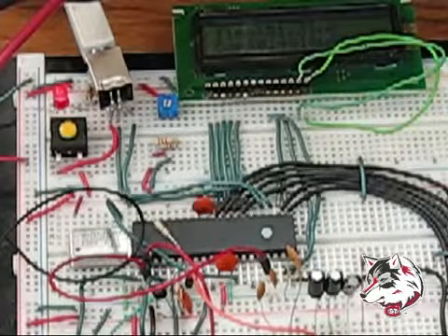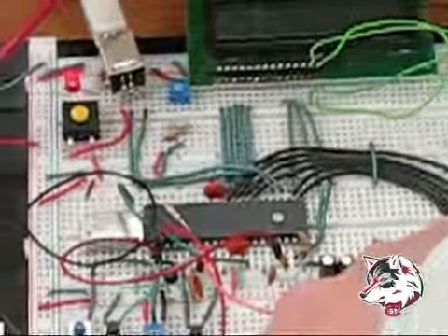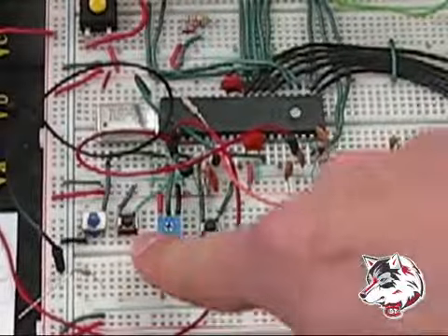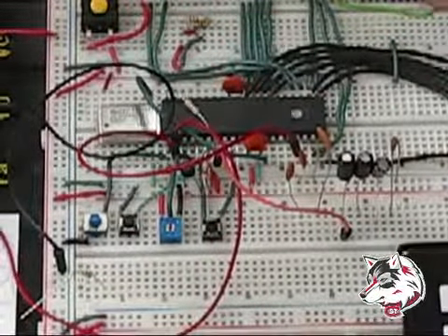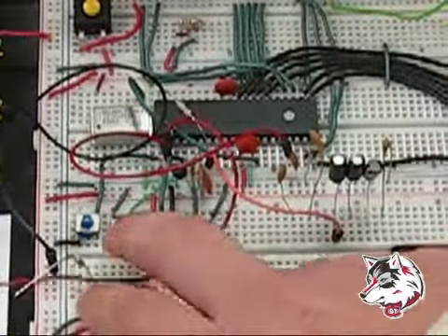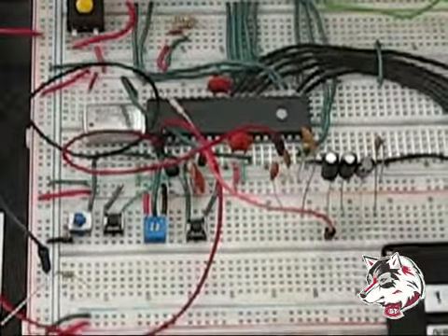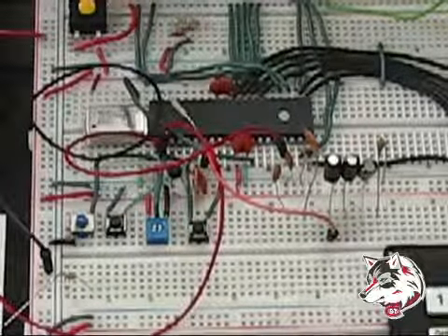So, that's a little bit about the breadboard side. You can see here we have a reset switch and then a bootloader switch. I'm running a USB bootloader, so you don't need to program the chip with anything like an in-circuit debugger or anything. Simply hold down this button and then click the reset button at the same time. And now we're in the bootloader, so we can just use something like a hyperterminal or in CCS, there's a built-in function.